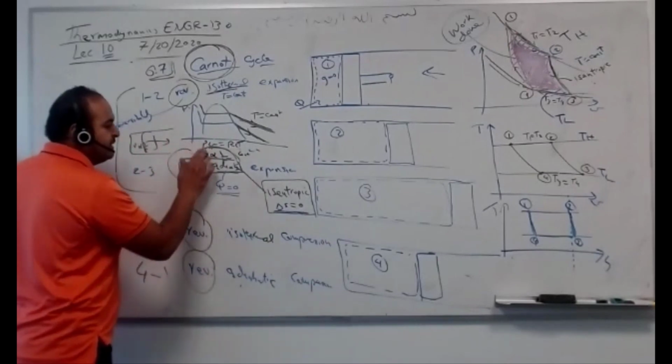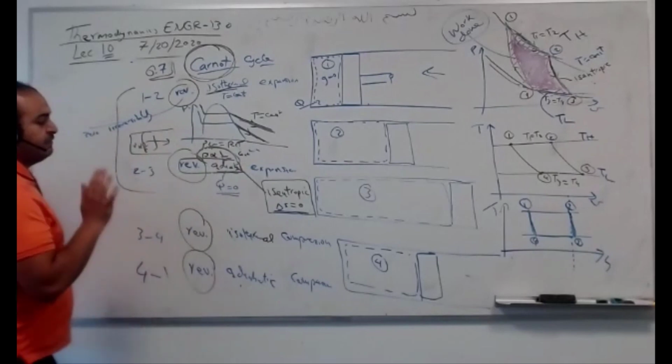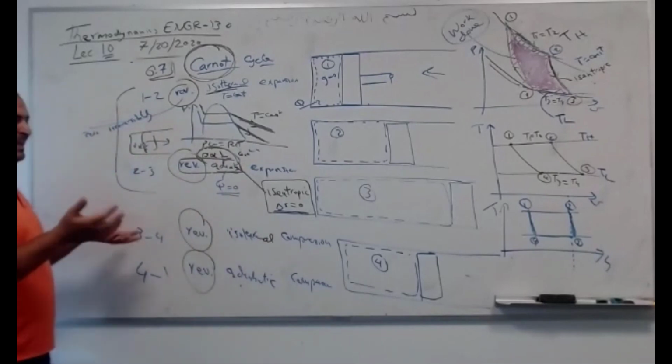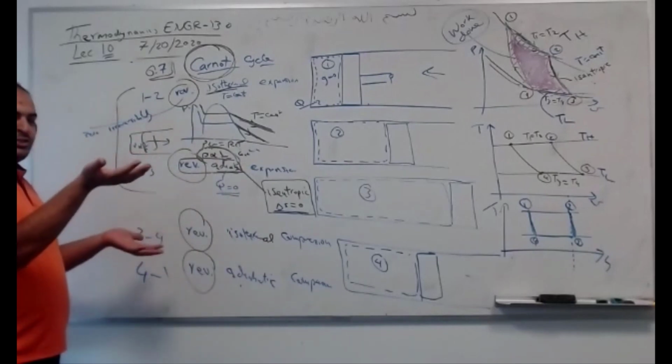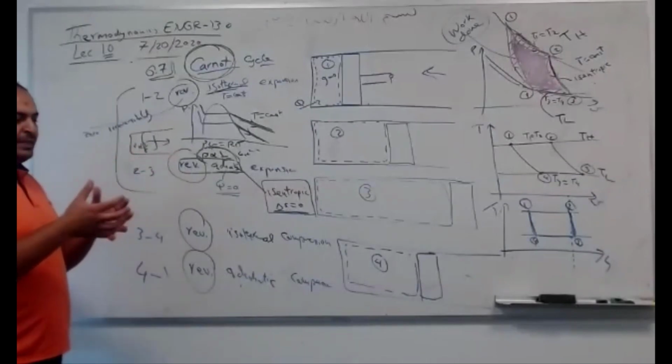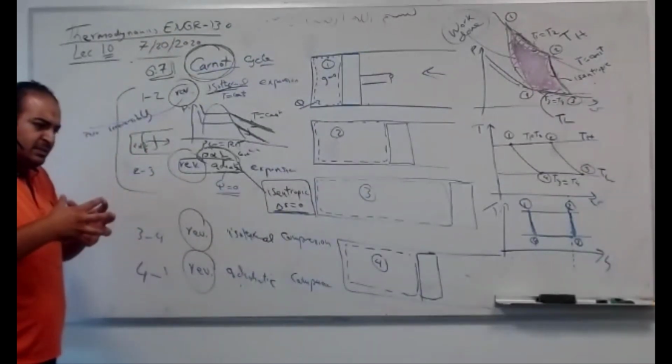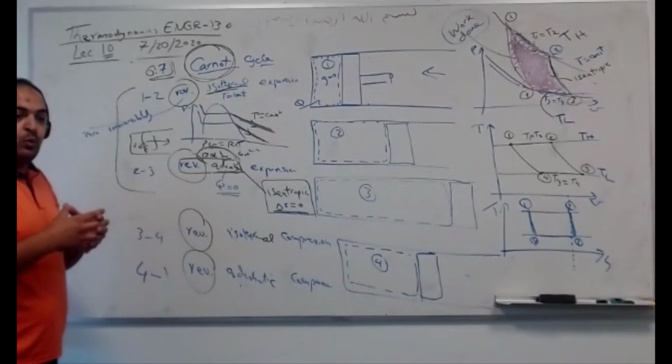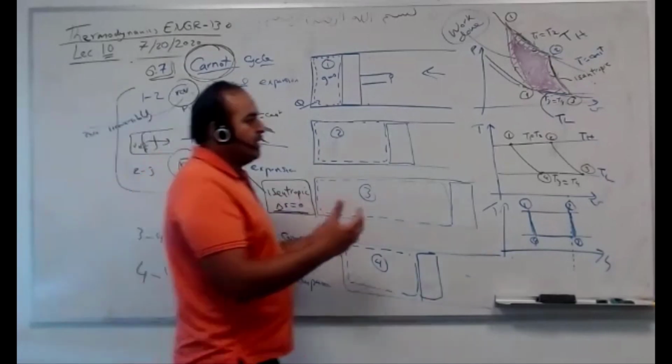In terms of gas, P is proportional to T if volume is constant. So typically, if temperature increases, pressure increases. If you get a gas and you compress it, what will happen? It gets warm and gets high pressure, correct? So usually think this way.